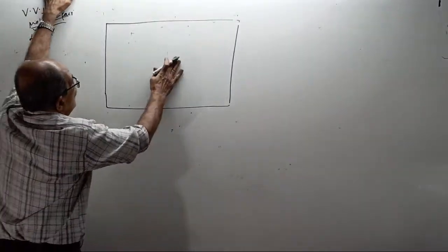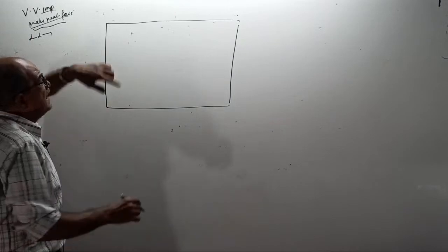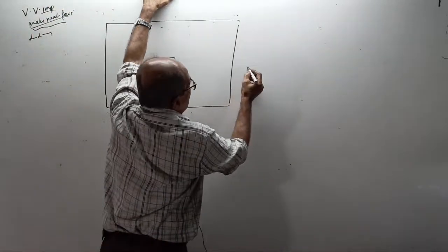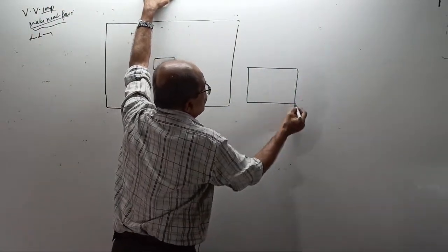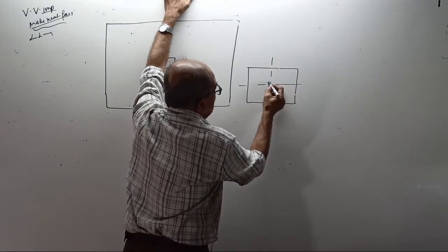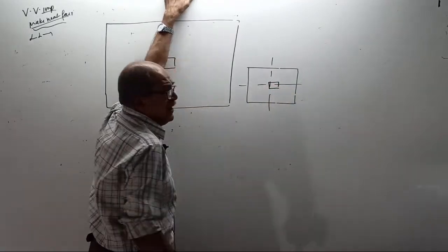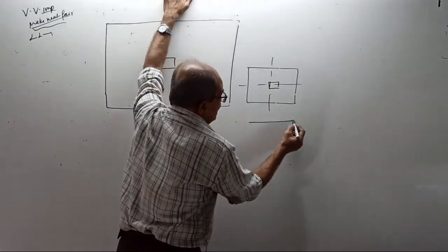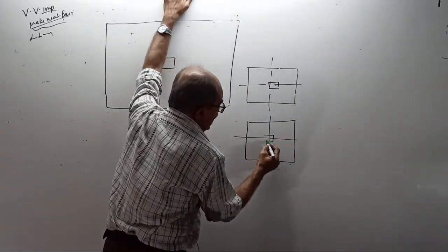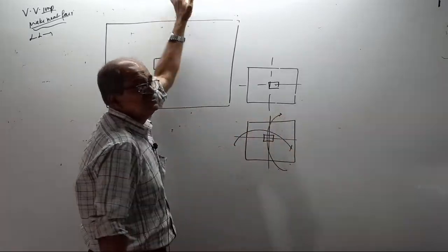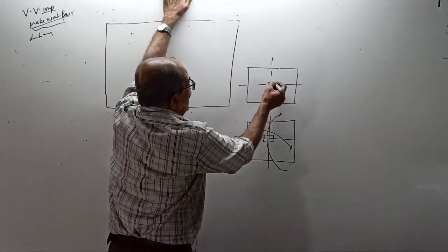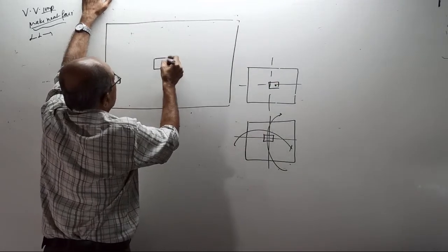Okay, start. Now, there is one case, and there is a second case. Column is concentric only. Actually, remember, make a note: if the column is eccentrically placed, too much eccentricity is not allowed. For example, if the column is eccentrically placed this way, then for design purpose, you take the column to be concentric only with M1, M2. When you consider P, actually P acting here will be shifted here. So finally, P will come here only.